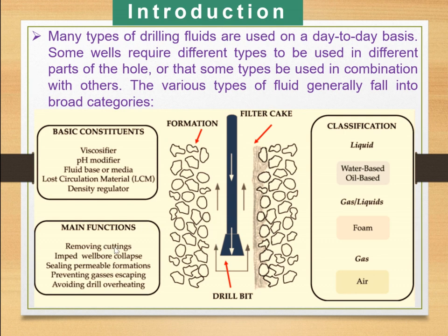Main functions of removing cuttings: impede wellbore collapse, sealing permeable formations, preventing gas escaping, avoiding drill overheating. Of course, this is liquid or fluid, whatever it is. When crushing and grinding take place, due to friction during coring, the drill bit temperature is enhanced, and that is why drilling fluids also regulate temperature, because when the fluid comes into contact, it will definitely reduce the temperature.